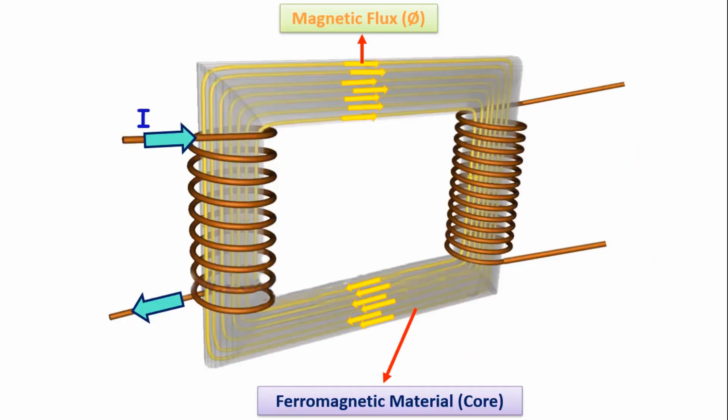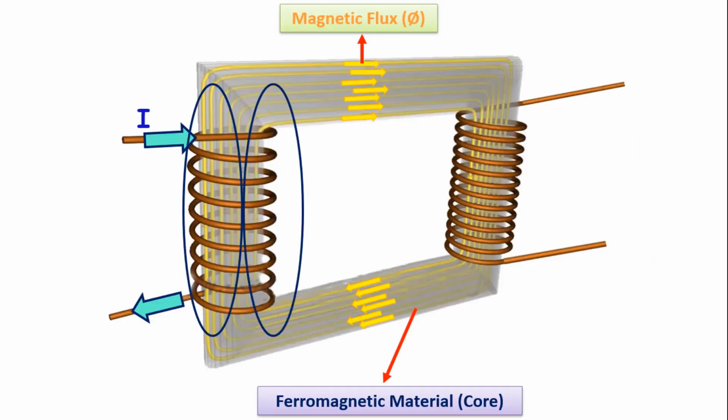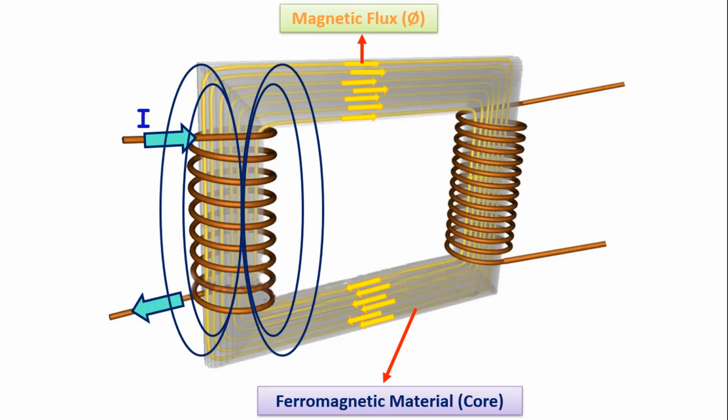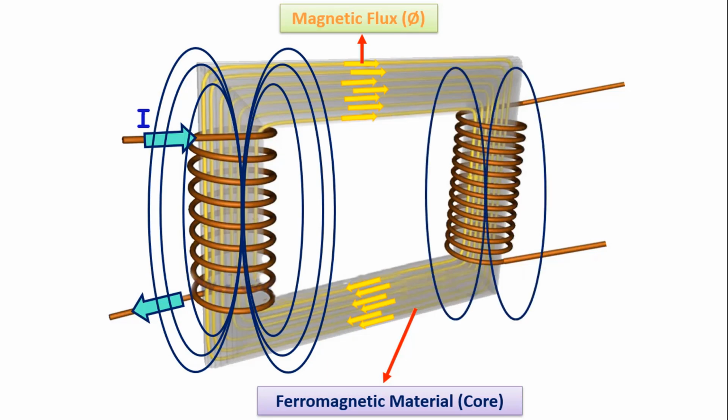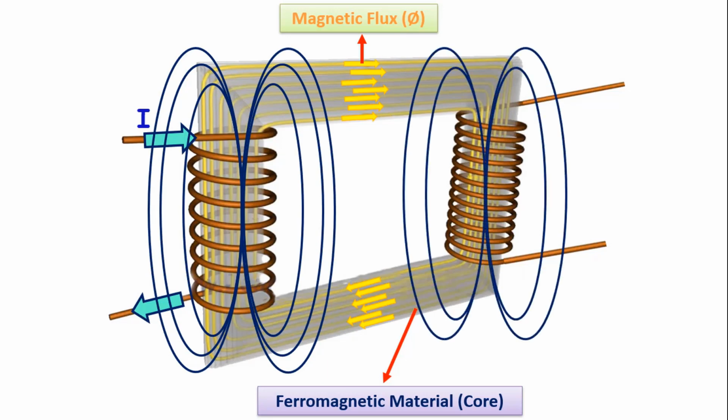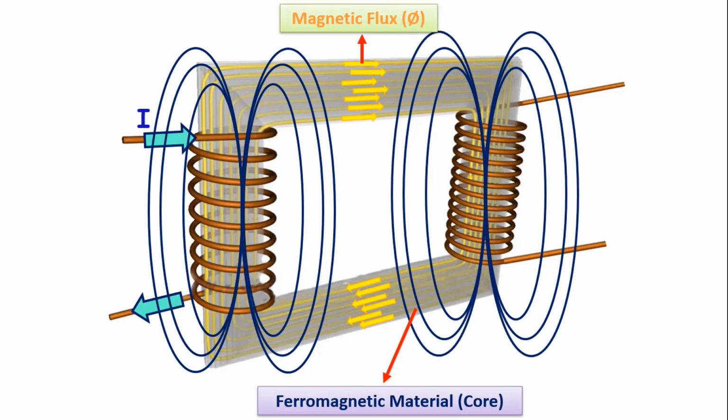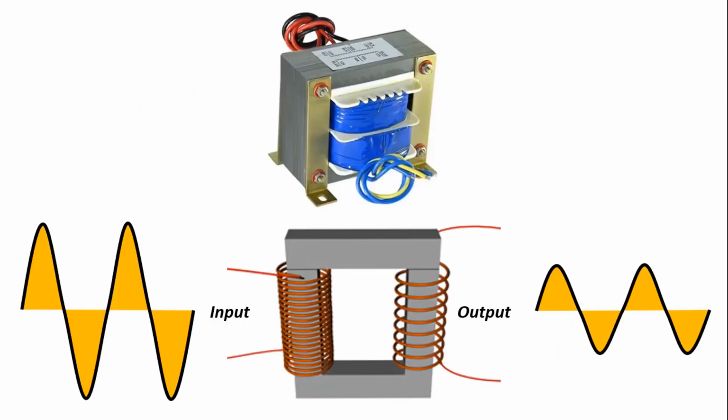When we wind these two electromagnet coils on an iron core and place them close to each other, a transformer is formed. Here, the AC voltage at the input creates a variable magnetic field on the coil windings. This magnetic field transforms into magnetic flux on the iron core. The magnetic flux in this core creates an AC voltage on the coil at the output, again with the effect of the variable magnetic field.